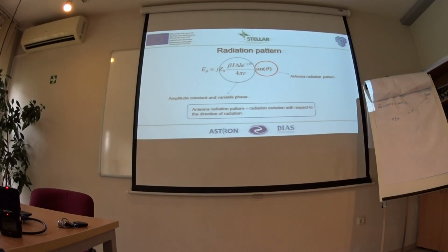But keep in mind, this impedance has nothing to do with current going through a conductor. This 120 pi ohms means that the E vector is, let's say, 377 volts per meter per 1 ampere per meter of magnetic field.